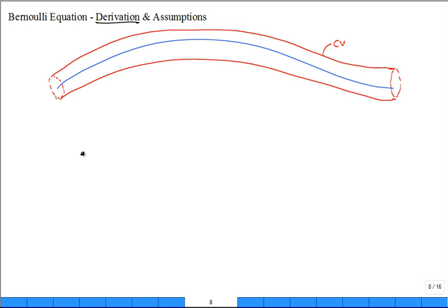I'll write it again as I just wrote it, and hopefully every part of this makes sense to you. The rate of change of energy in that control volume with respect to time equals the rate at which energy flows in with the heat, minus any shaft work, which they usually just call W dot CV. It's the work across the boundary of the control volume, because we've already separated out the flow work associated with the flow coming in and the flow going out.